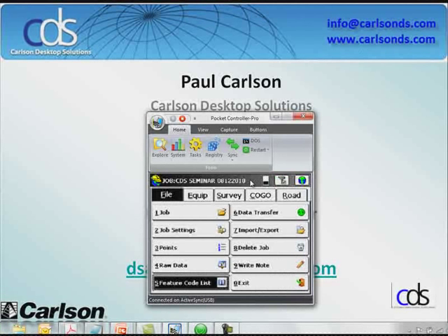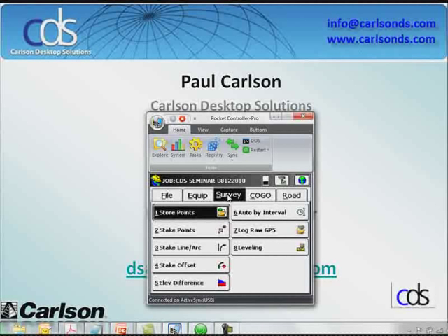My recommendation for field to finish is still go to the Office, set it up inside the Office, and transfer to SurvCE. Trying to sit in the truck using the little keyboard on the data collector to create a code library, not the way I would go. Okay, that's just me. I guess if you get paid by the hour, though, that's the way to do it.